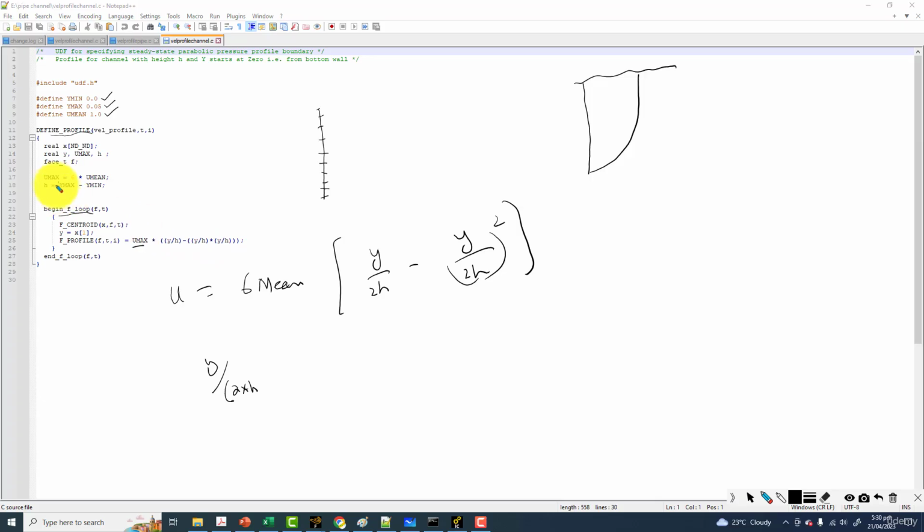So you can make y equal to 2 times, multiplication sign, then bracket y max minus y minimum. So there's no need to change the UDF equation here. Just change the things over here, and this will solve your problem. In this way, you can apply the velocity profile for the open channel. So only make the simple change over here. That's a simple thing.